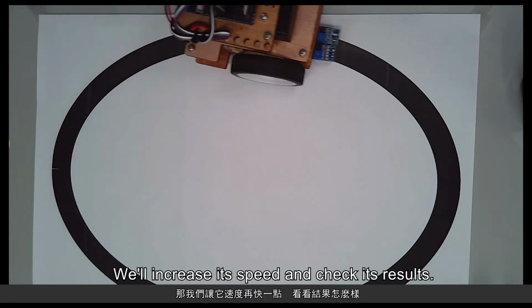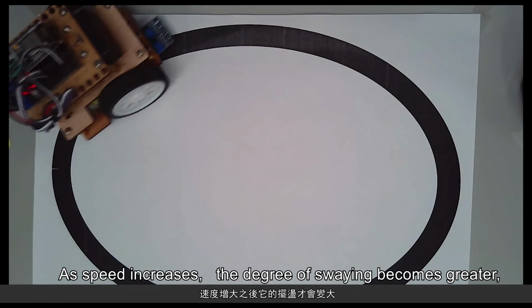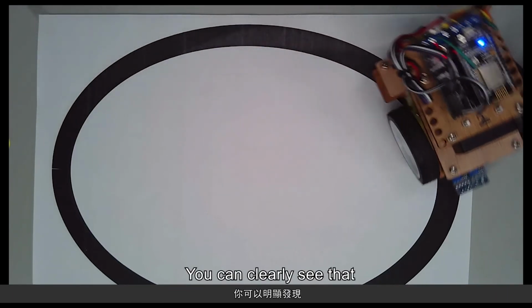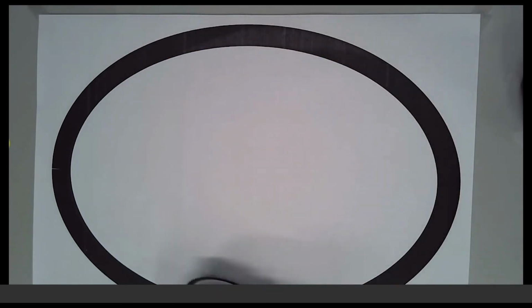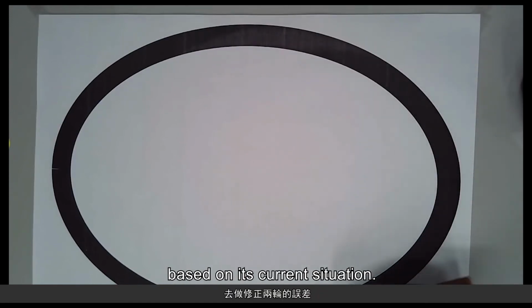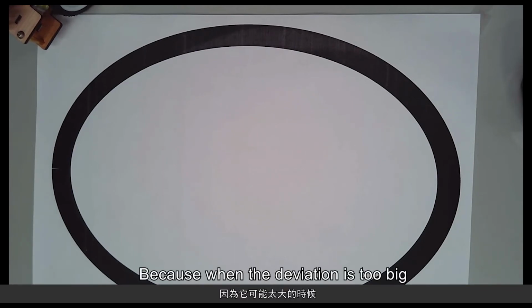We'll increase its speed and check its result. As speed increases, the degree of swaying becomes greater. Yet it's still able to adjust itself back. You can clearly see that the analog method and the digital method is different. The speed difference will not be a two-stage variation. It will adjust the wheel speed difference based on its current situation. It has already gone out of control. Why did this happen? Because when the deviation is too big, it cannot turn back enough.